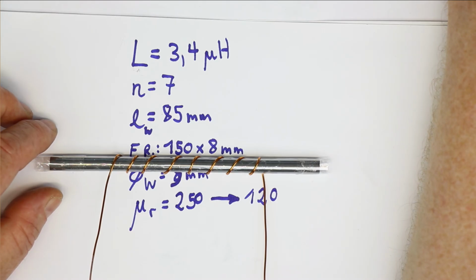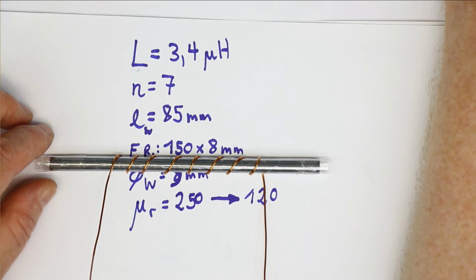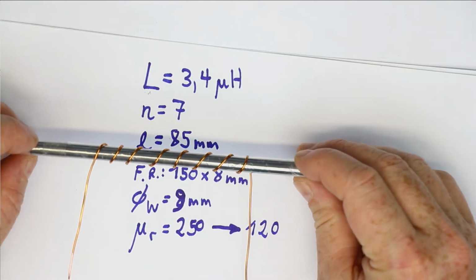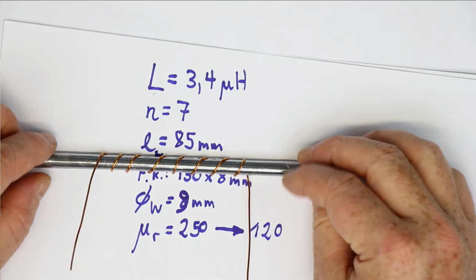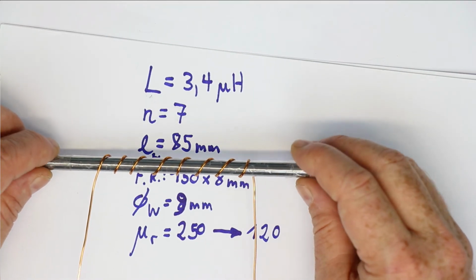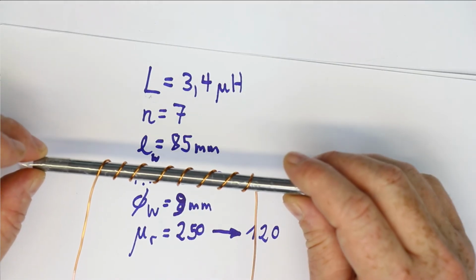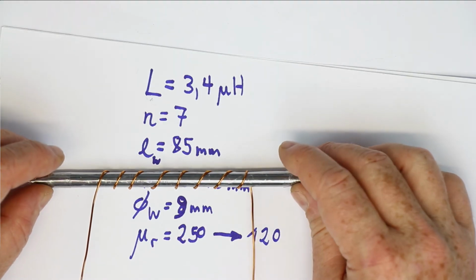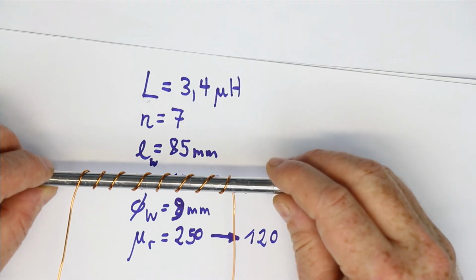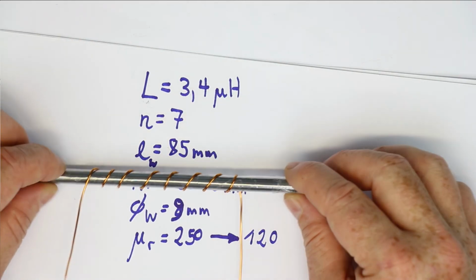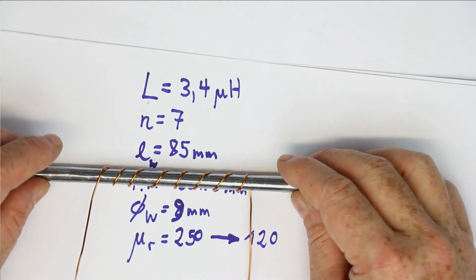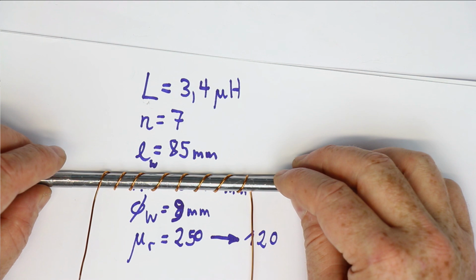And when you use all these parts of the recipe to make a high quality, high Q factor shortwave loopstick antenna, then you finally get a decent result in a small volume, and with all the other advantages that magnetic antennas have. You have a directional sensitivity, you have a small antenna, and well, that was it as a summary.